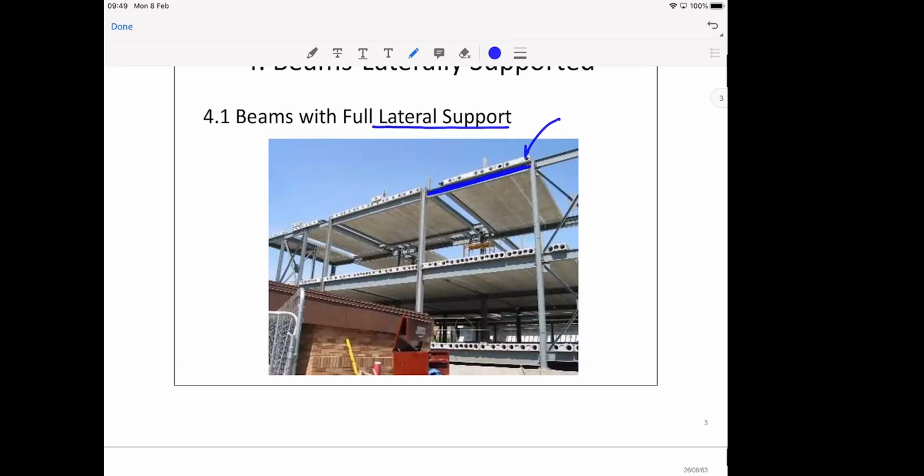And generally from structural analysis class number 1, you will know that this becomes the tributary width, right? Half the floor is going into this blue beam, and another half, for the sake of demonstration, will go onto that beam. So that becomes the tributary width of the red beam, and this becomes the tributary width of the blue beam.